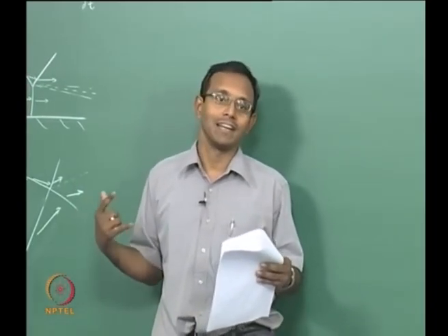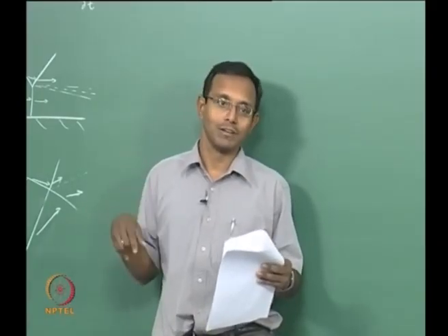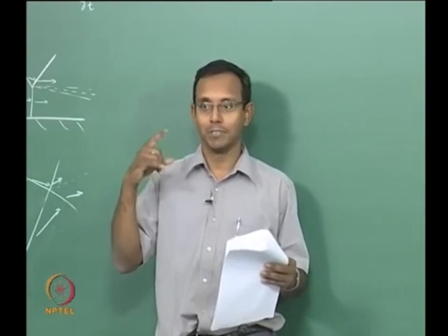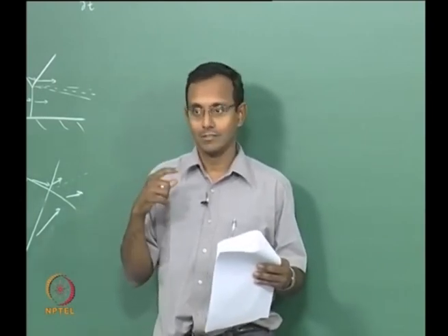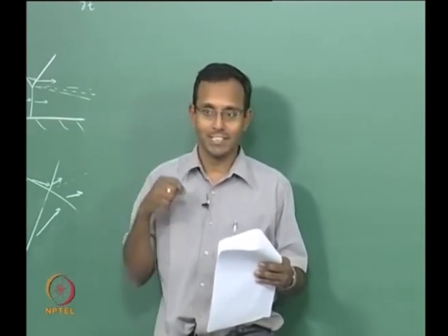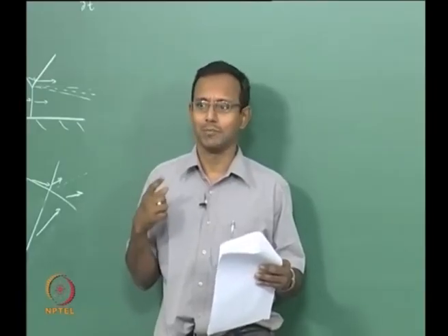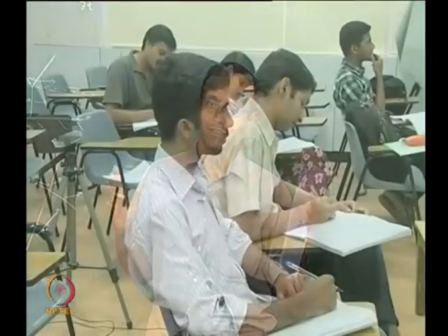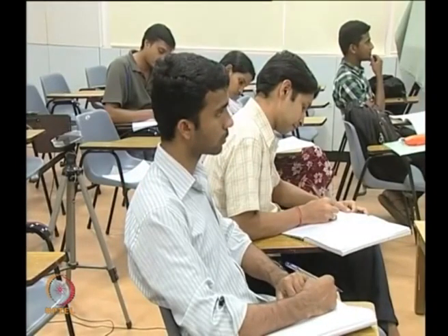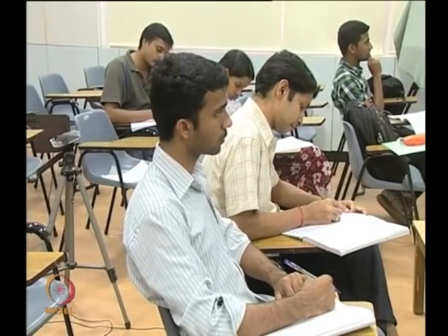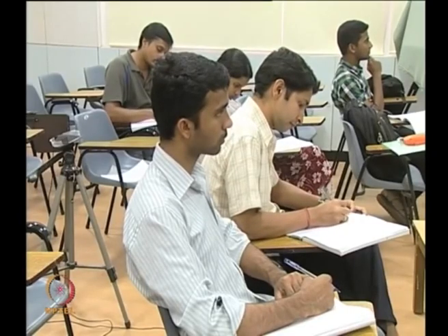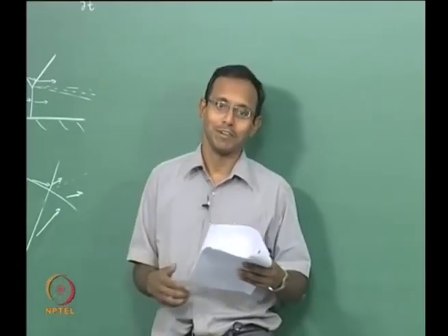So I will start neglecting this in my overall bulk, assuming that my bulk flow cross section area is much more than the viscous interaction area, which will typically be very small if my flow duct is big in size. When my flow duct becomes smaller and smaller in size, they become comparable. You will see that immediately after we derive the whole thing. There is a particular term called hydraulic diameter that will take into effect all these parameters naturally.